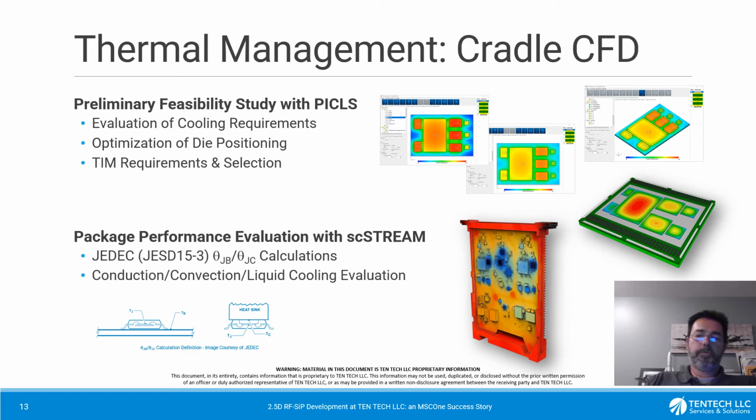Once we move to scSTREAM, we can perform more traditional thermal analysis, as in, is it going to work? Is it going to be too hot? What's going to be too hot? What can we do? And we also perform JEDEC types of calculation.